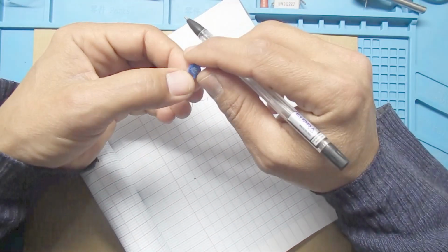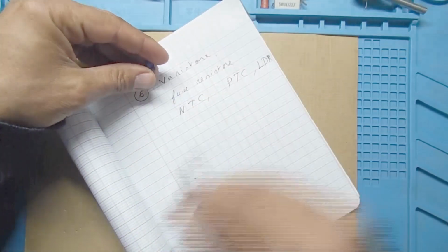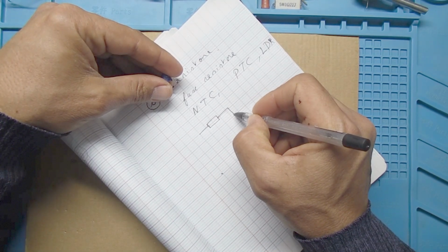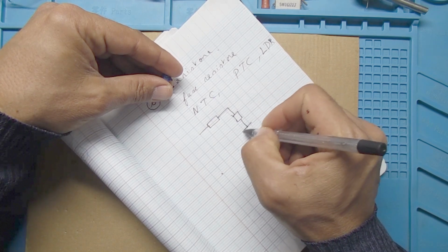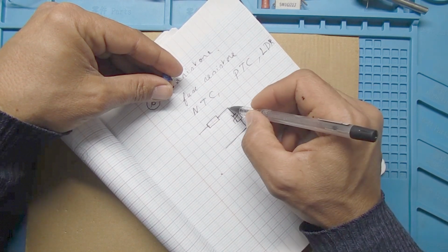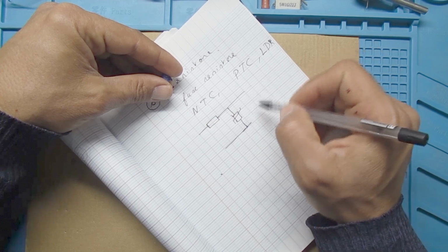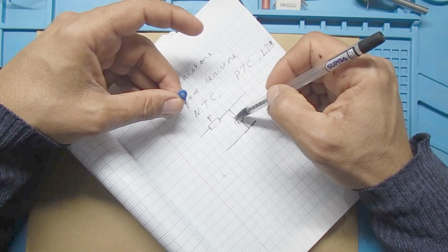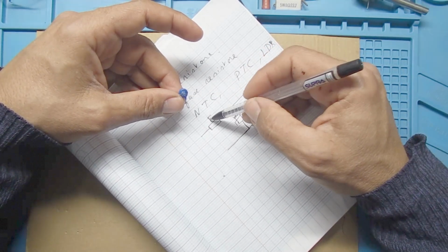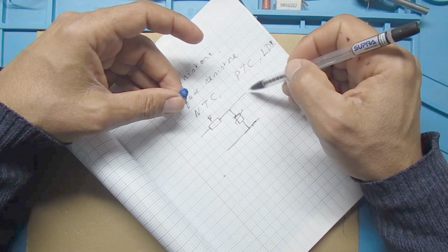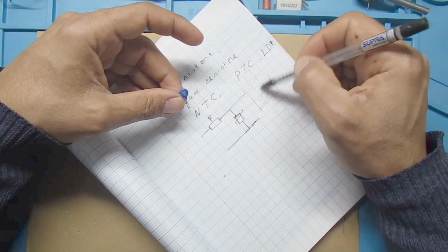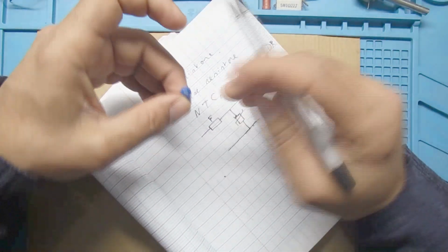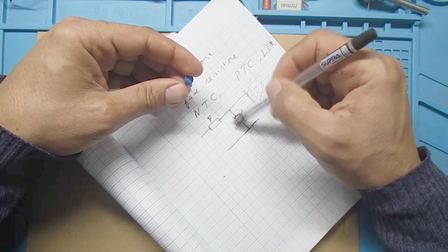We begin with the varistor. It's used to protect the circuit. For example, here they are often used after the fuse. Here we can find the varistor. Of course, here we can find the transformer or the bridge rectifier. Here we have the fuse. When we have an over voltage, the resistance of the varistor drops and causes the fuse to blow. So it protects the transformer or the bridge rectifier or the power supply. And in the repair, we need to replace only the varistor.